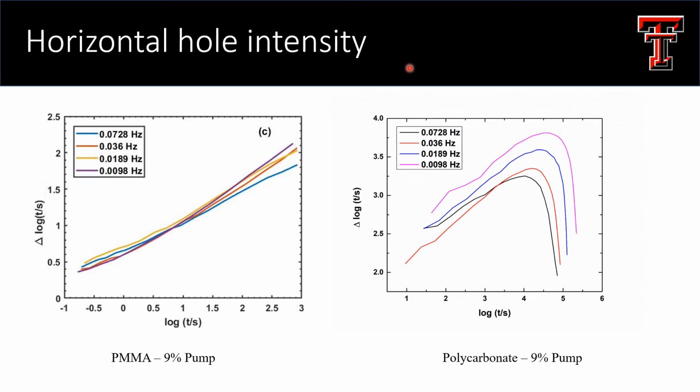In the case of PMMA, similar behavior is seen at lower pump amplitudes of 4% strain and 6% strain, but is not shown here. For 9% pump amplitude in PMMA, incomplete horizontal holes were observed as the relaxation spectra shifted to timescales which are greater than experimental times. This frequency-dependent hole position has been related to the existence of a broad distribution of relaxation times.